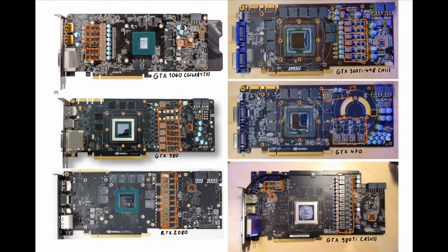Doubled is better than just having a big phase. So having a doubled configuration is better than a big configuration, and a big configuration is slightly better than a normal configuration. And yeah, so more phases, more better. And yeah, more switching frequency, also better for voltage regulation, but it will also put out more heat. It will make your efficiency worse.